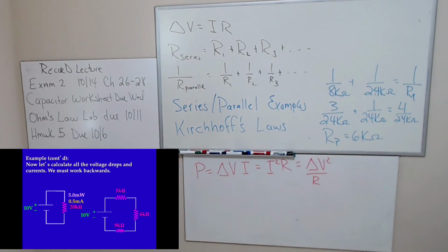This 5 kilo ohm resistor, if you take that 5 kilo ohms and multiply it by half, 5 times a half is 2.5. So I have 2.5 on the top resistor, 3 on the middle resistor. That gives me 5.5. I better have 4.5 left over to give me 10. And if you actually multiply 9 by a half, you will get 4.5.